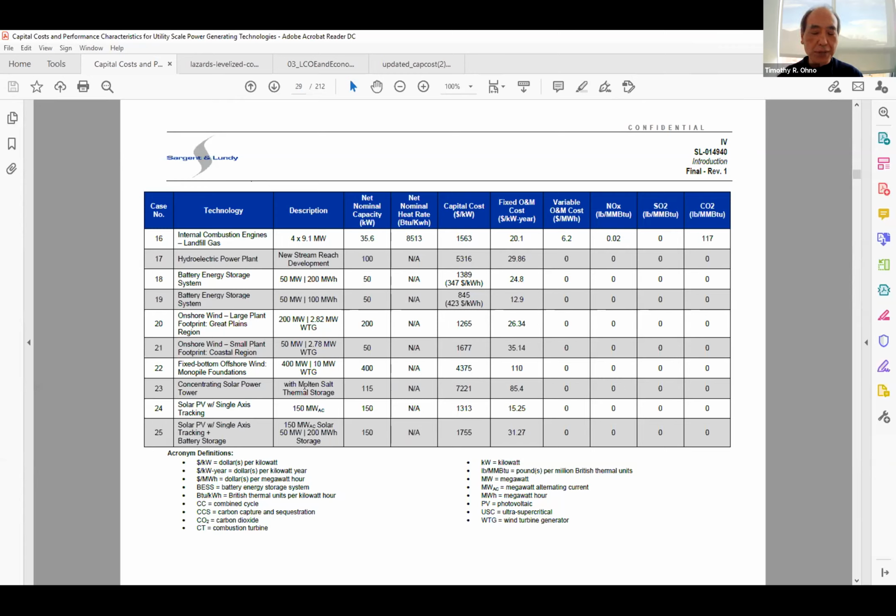And it won't be per year, because it's going to be the ratio of the cost per year divided by the production per year. And it's not just the cost in that particular year, because it's over the 20 years of its existence. Okay, sounds good. So it's just the variable O&M cost we have to convert. Convert in what sense? Well, you just said before that we'd have to convert megawatt hour to kilowatt year. Right. Not quite.